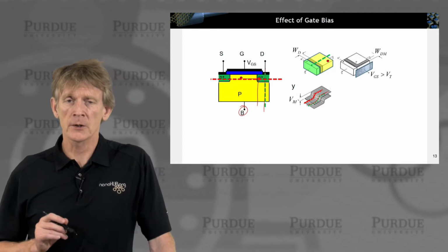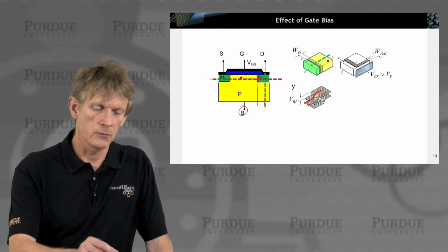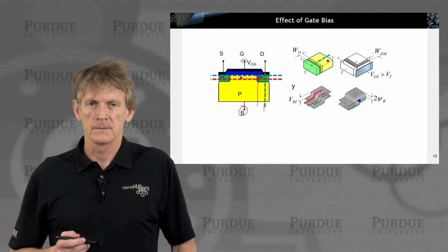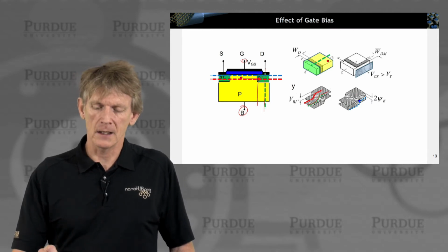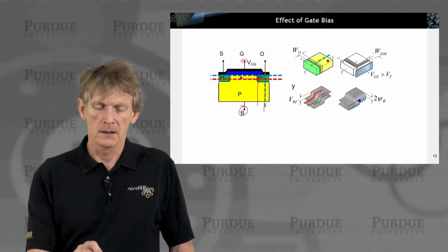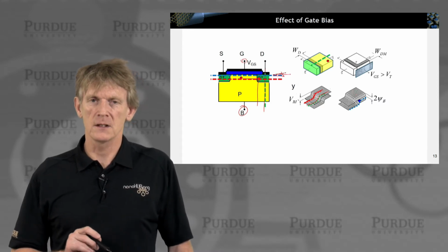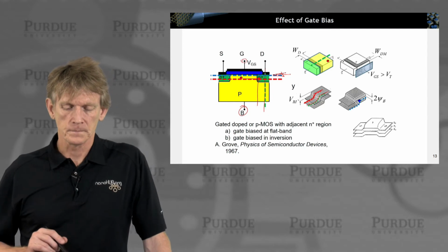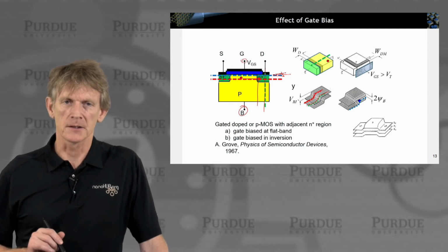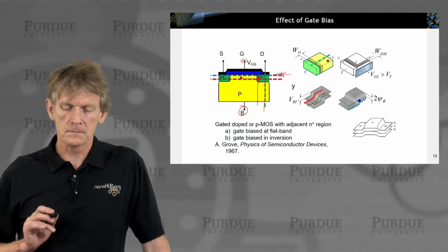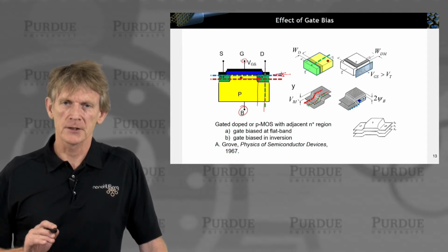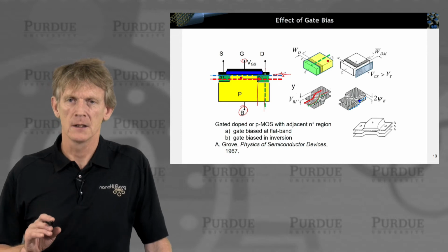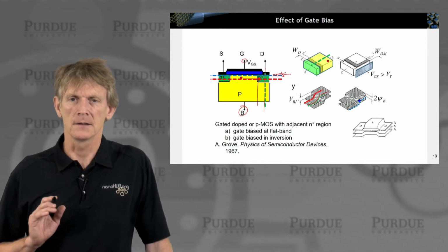Now, if we consider the gate potential in the structure here, so now we're applying a gate potential here, the potential landscape under the gate looks somewhat different. We're bending the bands down like this, and an electron traveling closer to the gate will see a different electrostatic potential. Okay? So, you've seen this sketch earlier in the previous section, okay? So the issue is potentials and charge distributions are getting a little bit more complicated. So you just have to walk through it carefully and stare at these images a little bit and get familiar with them.